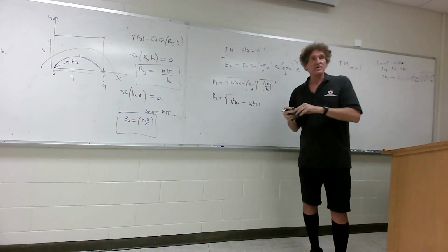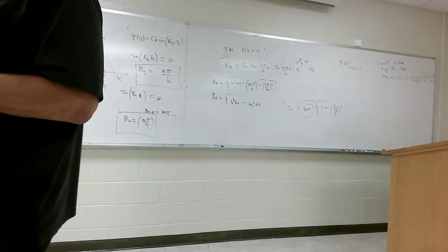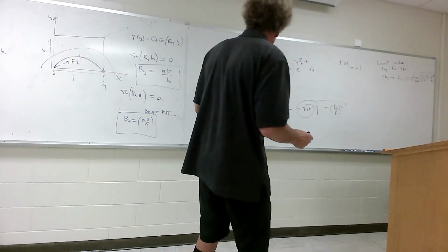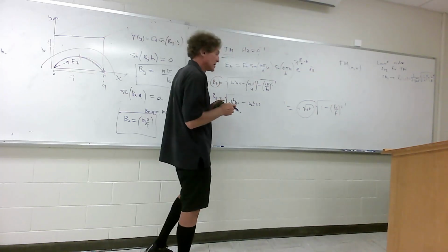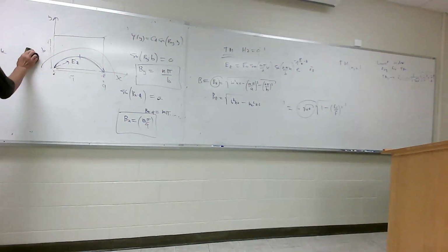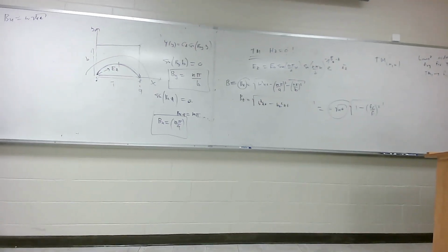That's for TM. We're going to see for TE, for transverse electric, you'll have cosines instead of sines defining the fields, and the lowest order mode will be the 1,0 mode. That is the cutoff, the lowest frequency that can propagate, period. You all with me, class? One more thing on this topic: this is beta in the z direction. While I'm on it, what's the wavelength? I know I'm throwing a lot at you, and you'll get plenty of example problems.